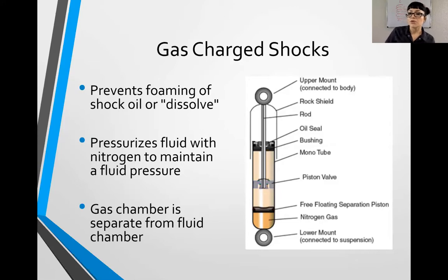If they sort of start to clump up in areas that we don't want, we can get a change in, not a spring rate. So if my shock absorber, first off, let me back up here. How does the shock absorber work? Because I can't explain why air is bad if we don't know how the shock absorber works. Our shock absorber has a cylinder, which is like a tube, right? And we have a piston that is attached to a rod that is moving through fluid. This piston is moving through fluid, right?